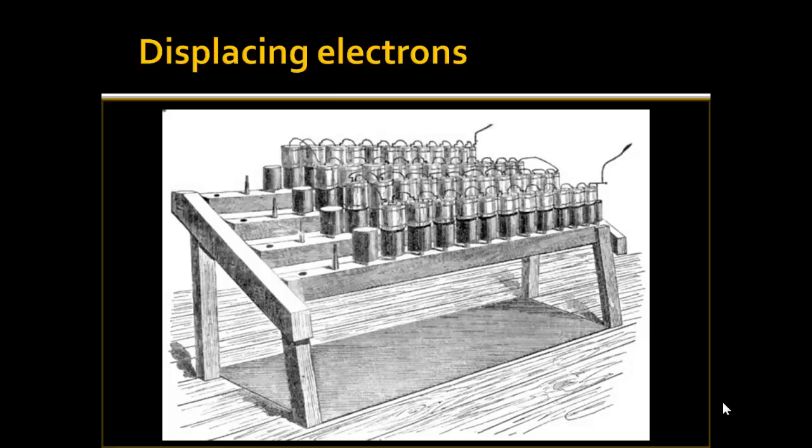In the beginning, when it first starts doing that, it's very rapid. But remember this, as it keeps pulling negative charges away and leaving it positive, the field strength between those two poles on the battery starts increasing. In other words, the voltage becomes greater and greater until at some point the force to pull the negatives back to the positives equals that of the acid pulling them apart, and then it stops charging. At that point, it is in equilibrium, and that's the highest voltage that cell can attain.